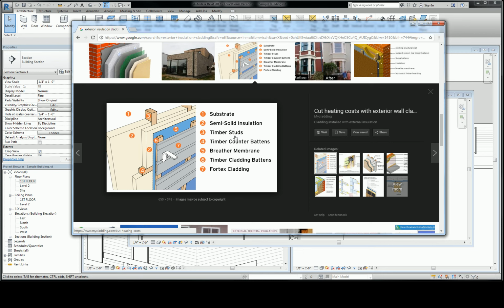Oh, well, I think walls are already a family, right? Yeah, so that's an interesting, important thing to discuss, guys. It's really important to understand what types of families there are in the Revit environment. Walls, floors, roof assemblies, they're all what's called system families. You can't custom modify the parameters of system families. They're hard coded into Revit. You can only do layers. You can't create special features for it.